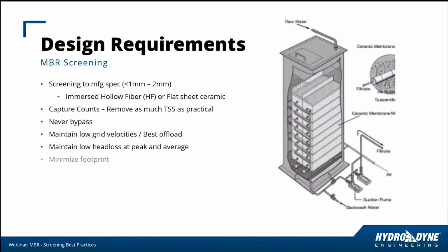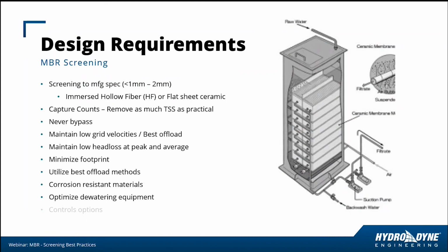Looking at design requirements required to protect a membrane biological reactor, the screening is set up to manufacturer spec. So it's generally very small spacing required, and this is for most immersed hollow fiber and flat sheet ceramic membrane systems. Also, capture counts. The idea is to remove as much total suspended solids as practical coming into the wastewater treatment process.